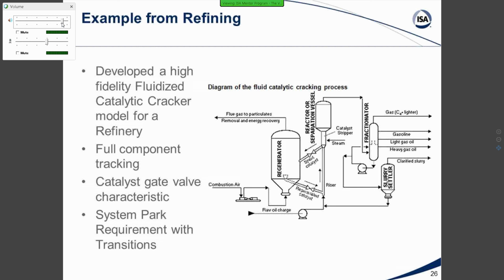Now, what this then requires is that essentially you have an entirely new steady state operation where you have steam, and you'll notice in this picture here that this goes over to a fractionator, and this column then collapses because it loses pressure. Everything feeding the column is just water. So this obviously is much more complex of a situation to model.